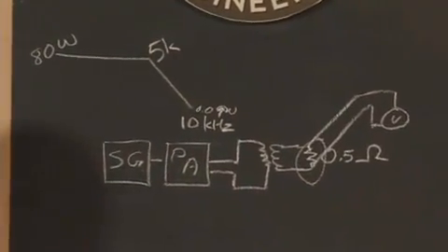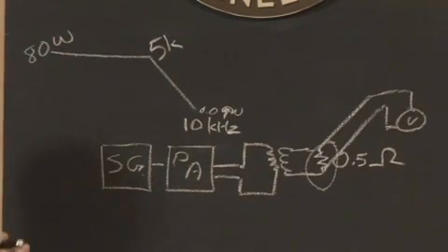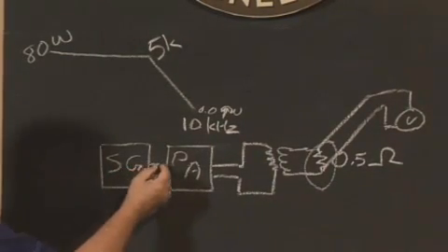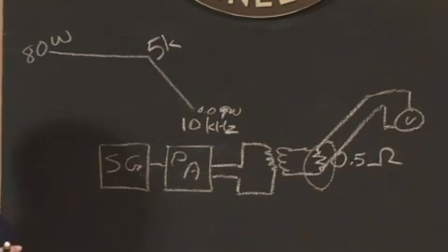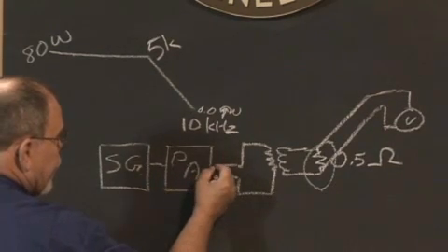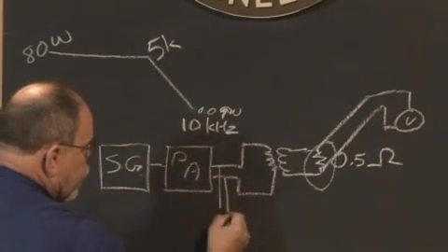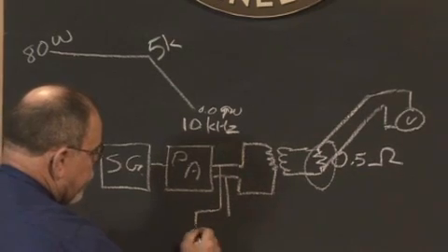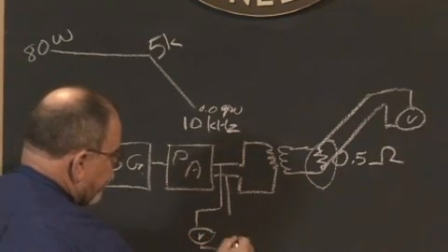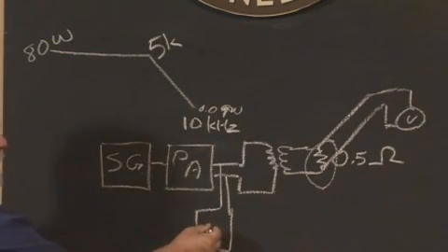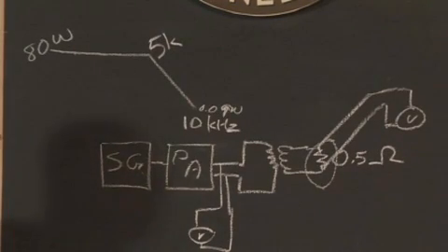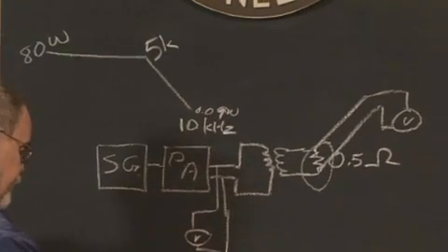So this is a setup that we can configure for getting this pre-calibration done. When we do this, we need to record what values we're applying. So at the output of the power amplifier, we need to put a voltmeter of some form to measure what we're applying on the primary circuit. So this becomes our reference point once we have gotten these levels established.